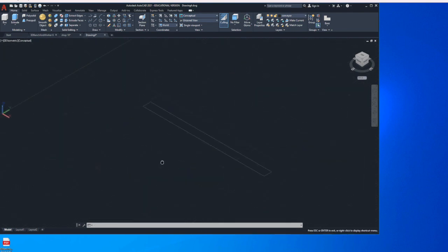Now I'm going to basically use the extrude command to extend this into 3 dimensions, but I'm going to do something slightly different because I don't want this to be just a solid object. I want this to be an empty box that I'm going to fill. And in contrast to the building itself, I'm not going to worry about the thickness of the sides of it because that's going to basically be sheet metal, and for practical purposes we'll represent that with just a line.